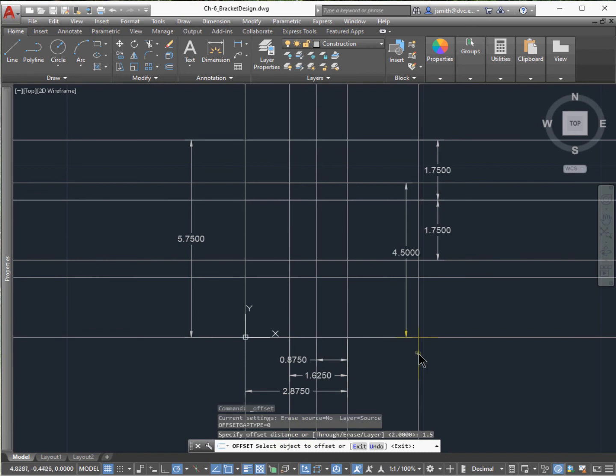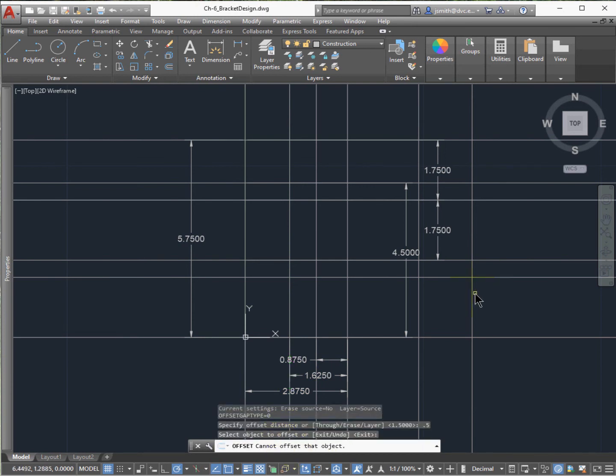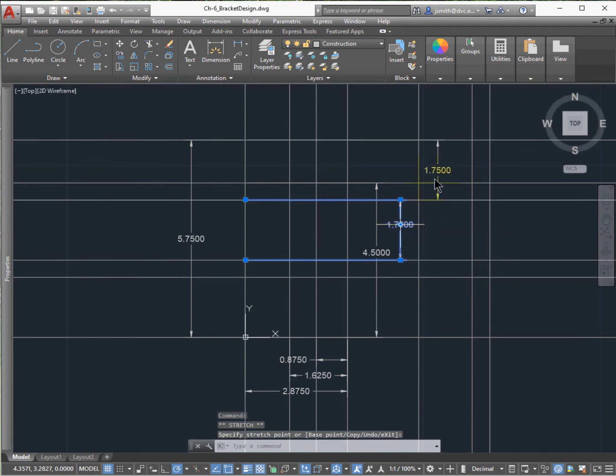All right, select the part. Let's go over. And then if I look at my drawing, there's actually a half an inch portion of it. So I'll go ahead and work from the outer size of it here. So go ahead and type in 0.5, push enter, and then click the outer line and move that in. Oopsie. All right, so let's get those dimensions out of our way. All right, I'll go back and clean up that. That last line is actually on the wrong side of the part. That's okay, we can modify this later.